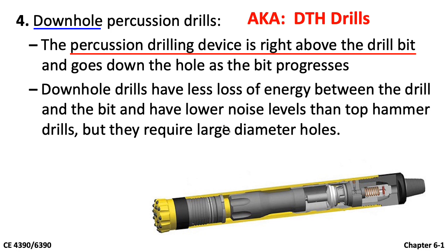Since the hammer energy is directly transferred to the bit, it has less energy loss. Also, it has a lower noise level than top hammer drills. However, this type of percussion drill can only apply to large diameter holes.